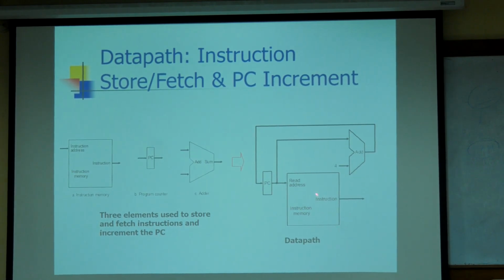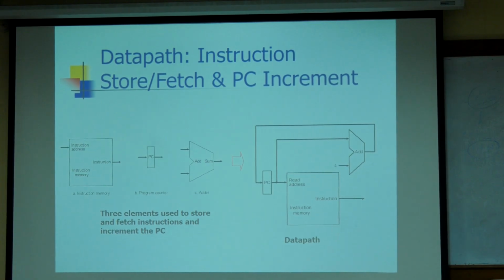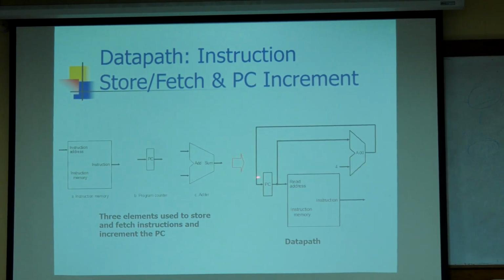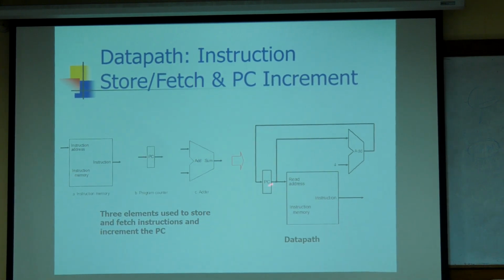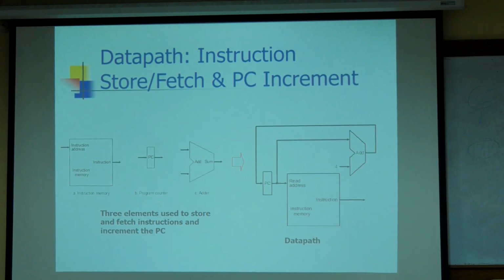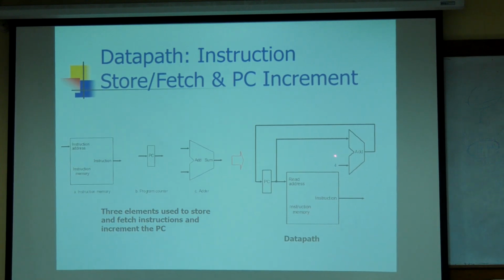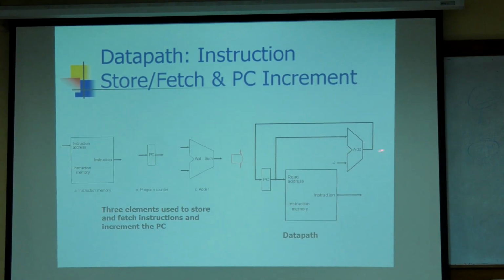What is the address size? I already told you, the registers and everything are 32 bit: 32 bit address bus, 32 bit data bus. The internal architecture is 32 bit. So this address is 32 bit and the program counter is also 32 bit, indicating a 32 bit address. So this input is 32 bits, and the constant 4 is also in 32 bit format. Then this adder is a 32-bit adder. So a 32-bit adder is required.